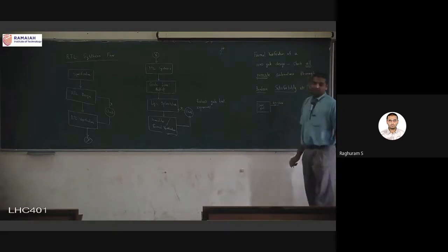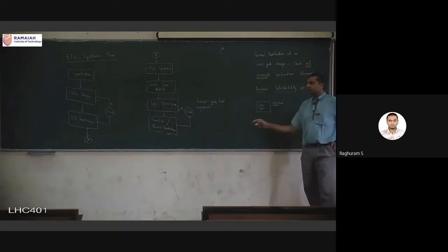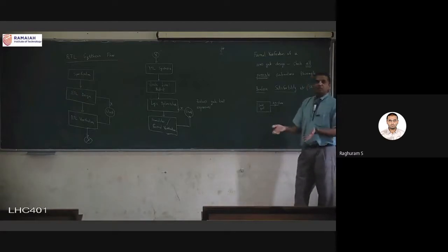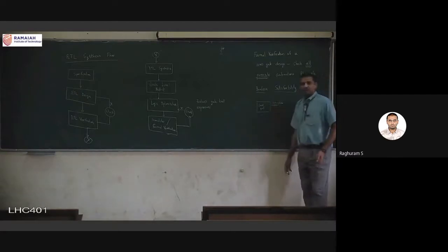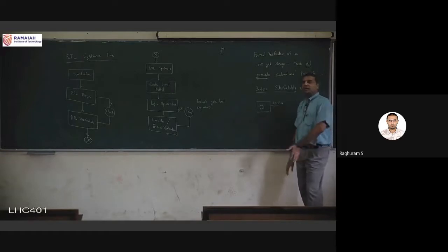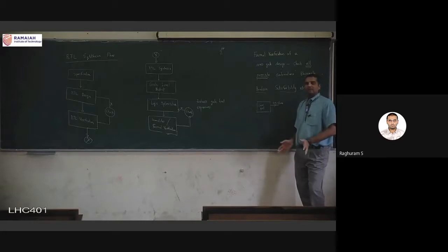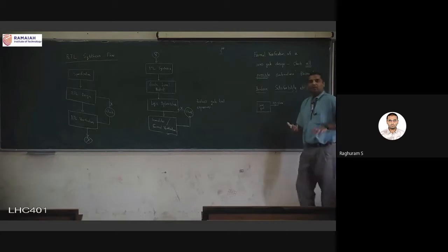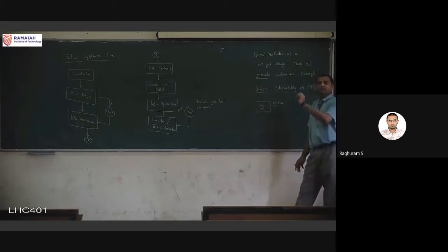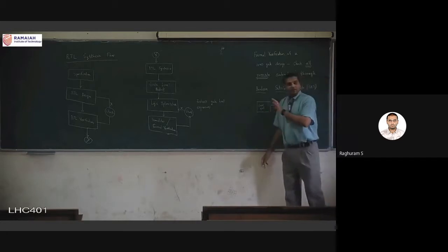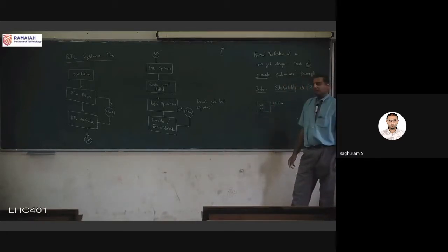is an error, now the problem with simulation is, I don't know which input combinations will produce this error. So I can try 1000 inputs, and if 1010 is not coming, then I can say, as far as these inputs are concerned, the circuit looks okay, let's go to the next step. But the problem is, I have given only 1000 inputs. It might be requiring 1050, or if I come to 1075, I might be generating this error, and that might be much larger also. That is the main problem with simulation.